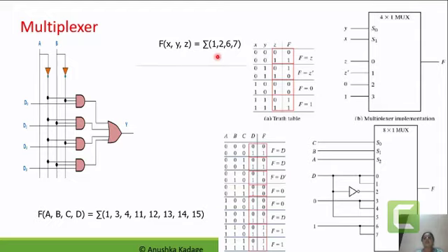So the number of select lines for the 4:1 mux will be two select lines, S0 and S1. So we have now obtained how many inputs and how many select lines there should be, but now we have to define how the function output will be created and what will be the assigned input variables for the multiplexer.